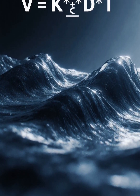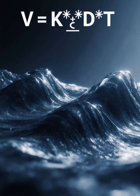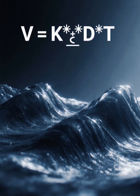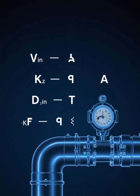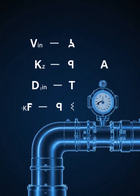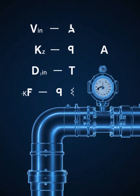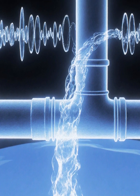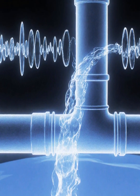Ultrasonic sound waves are sent through the fluid, and the time difference between upstream and downstream signals reveals flow velocity. Formula: V equals K times D times delta T, where V is liquid velocity, K is flow tube constant, D is distance between two transducers, and delta T is difference in time of flight. With flow, sound will travel faster in the direction of the flow and slower against the flow.